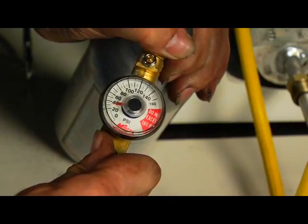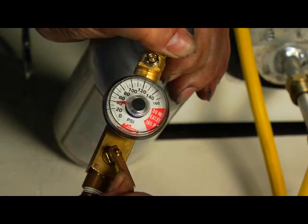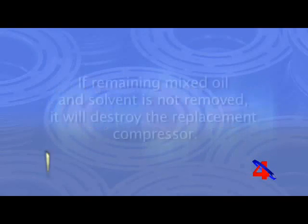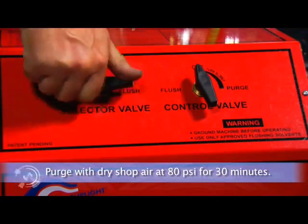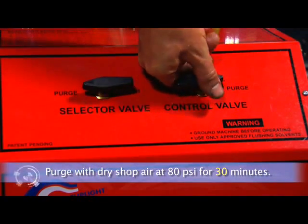Controlling the flow of solvent at 40 psi allows the solvent enough time to mix with the contaminated oil and clean the passageways. After the solvent has cleaned the evaporator, a comprehensive purge must take place. A few ounces of mixed oil and solvent will remain inside the evaporator. If it is not removed, it'll destroy the replacement compressor. The only way to get it out is to purge with dry shop air at 80 psi for 30 minutes. Not 15 or 20 minutes, but 30 minutes.